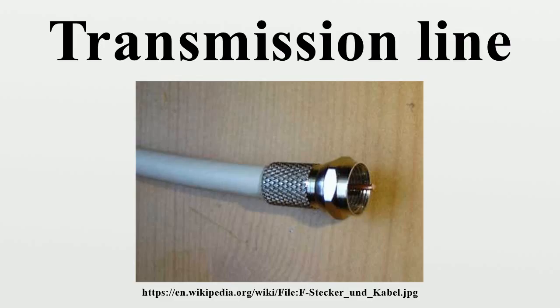However, at frequencies for which the wavelength is significantly shorter than the circumference of the cable, transverse electric and transverse magnetic waveguide modes can also propagate. When more than one mode can exist, bends and other irregularities in the cable geometry can cause power to be transferred from one mode to another. The most common use for coaxial cables is for television and other signals with bandwidth of multiple megahertz. In the middle 20th century they carried long-distance telephone connections.